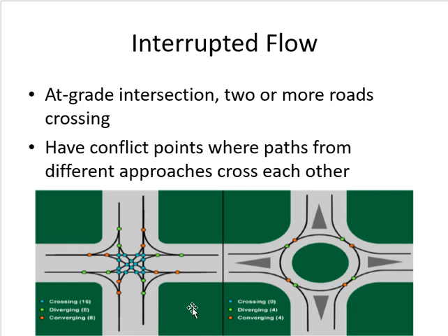Okay, one thing you have to keep in mind is that once the conflict point happens, after the conflict point we don't consider them as different cars. You consider them as one vehicle, one car. So you see this one, two cars have already merged. Now I will not make two converging points here, because these two are now one. Okay, they already converged. Similarly, this one, after diverging from here, this is one car, this is another car.